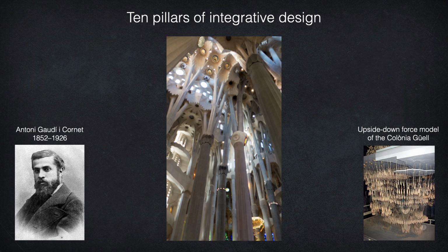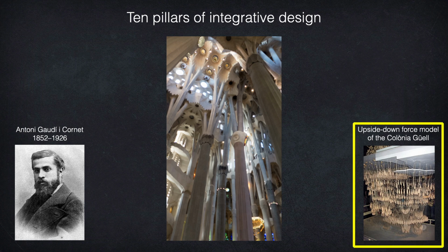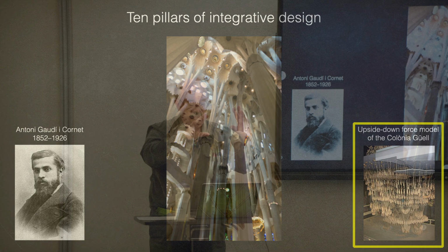Now, do you happen to know how he did the structural design of those soaring stone arches and vaults and pillars long before we had computers? Well, you can go down to the basement and see an upside down physical scale model with strings or fine chains suspended from posts so they would hang down in catenary curves, equally distributing their gravity-induced tension along each chain.